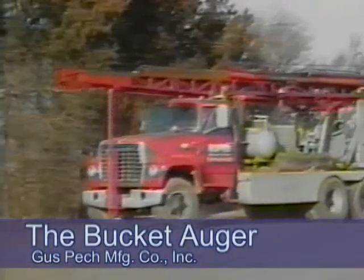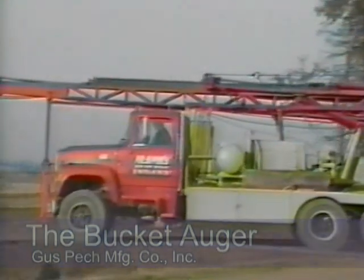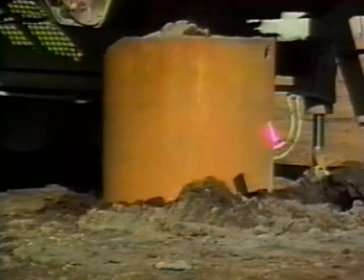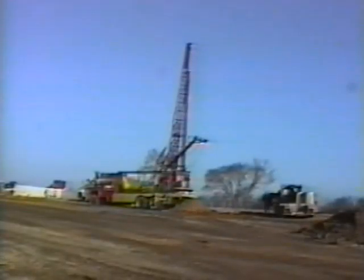The bucket auger is used primarily in unconsolidated material for constructing large diameter boreholes ranging from 24 inches to 48 inches. These large diameter boreholes are ideally suited for areas producing low-yielding wells in aquitards. The drilling system consists of a truck-mounted drill with a separate deck-mounted engine, which must be capable of generating enough torque to overcome the friction associated with drilling such a large diameter hole.